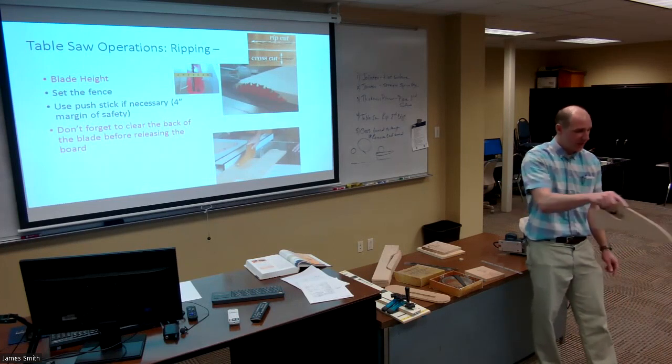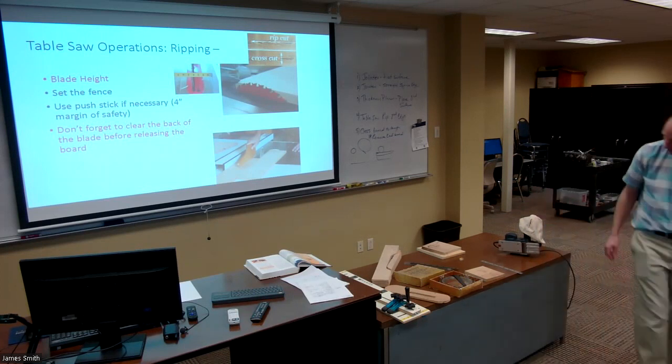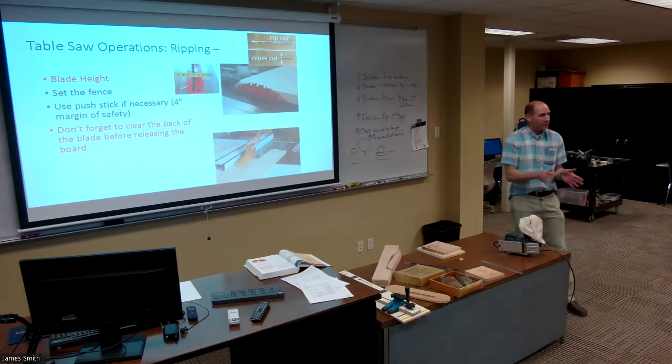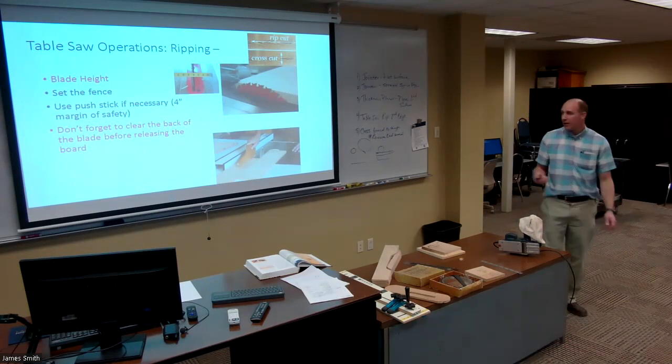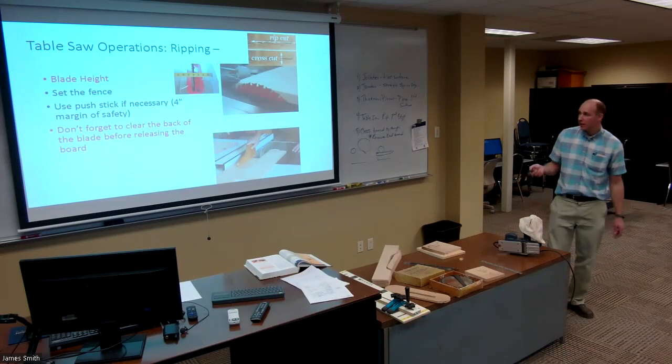And so a push stick like this might be better suited for shorter boards. But never get within that margin, what did we say, a 4-inch margin of safety? If you're cutting a board that's narrower than 4 inches, and you have to hold it somewhere within 4 inches, use a push stick.